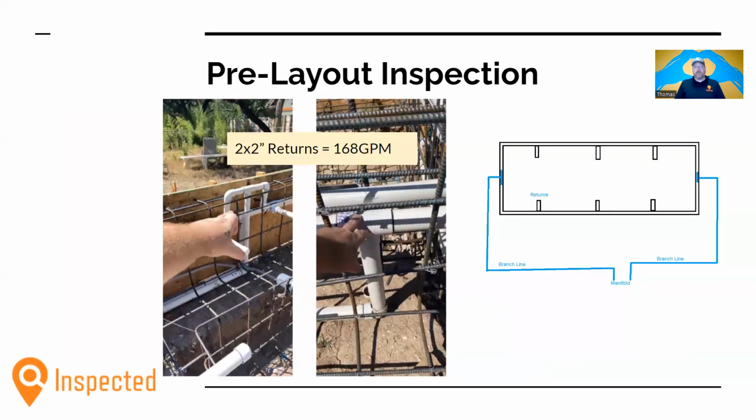Additionally, we have a consistent challenge when it comes to spas, in that when it's in spa mode, the water comes out of one pipe, traditionally goes back to the equipment set, is filtered, sanitized, heated, and returned back to the pool with one pipe.